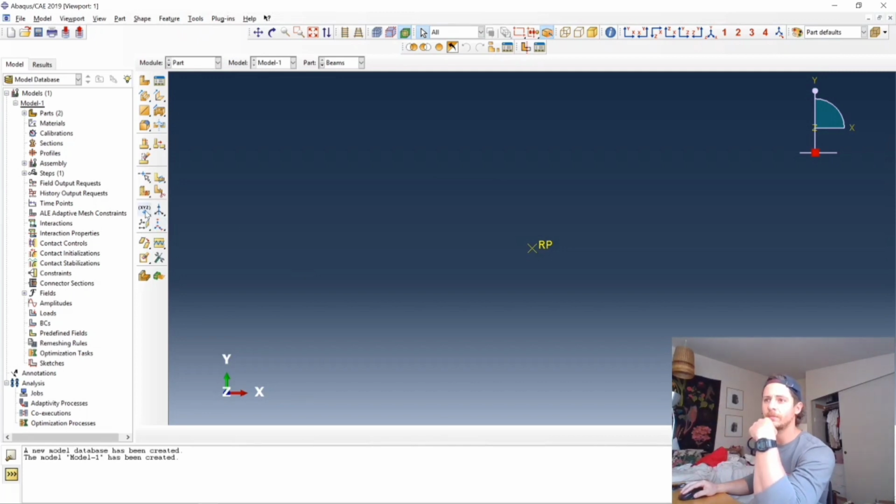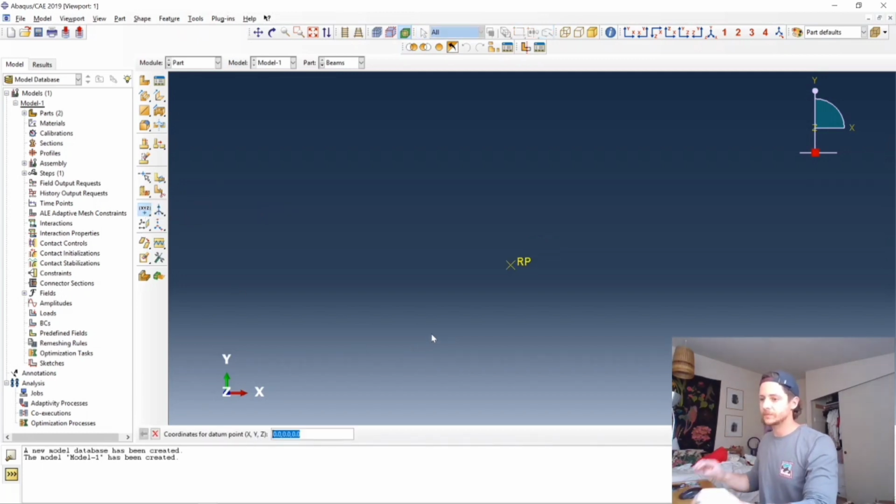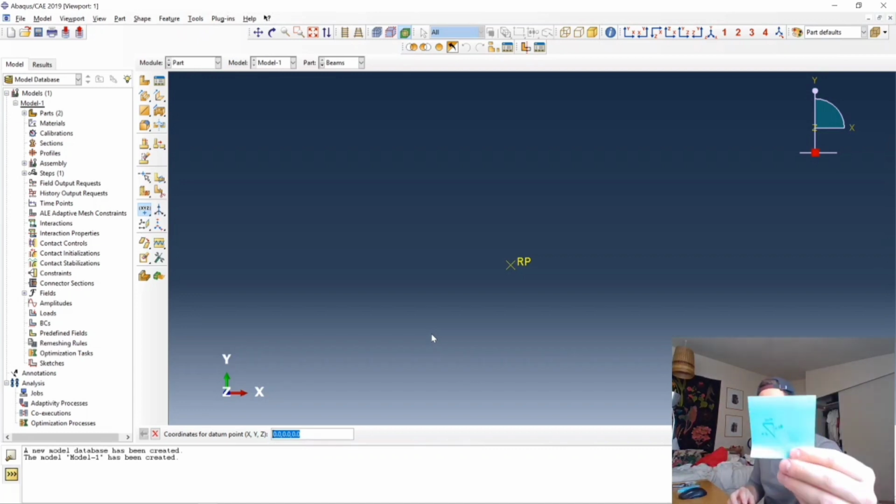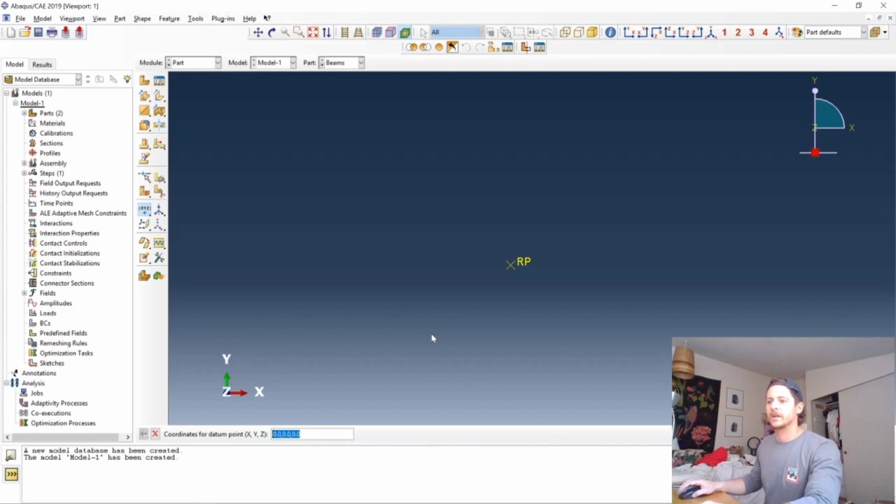That's fine. Now we want to enter the coordinates of some more points. So we'll click this guy. For the 4 other points that we're going to need to make this beam standoff, if the beam length is 0.2 meters long, let's just go ahead and make a 3, 4, 5 triangle. And so we're going to offset it vertically by 0.16, and then horizontally by 0.12. So it looks something like that. Hopefully you guys can see that.